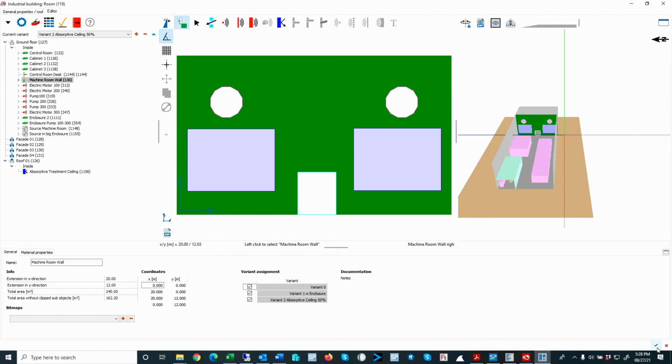If you want to save your geometry or your input in between and not necessarily close your model, you can also do a Control S as a hotkey, and that will also save the model. Now here a few other things before I close it. There's a pre-flight. So this pre-flight is good to double check if you have any problems in the model. So here I just initiated the pre-flight.